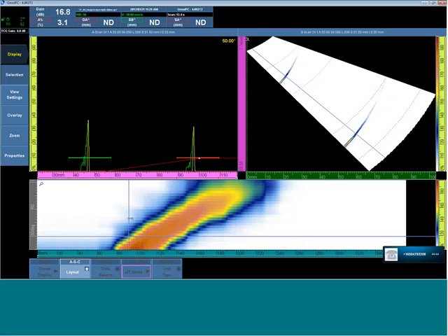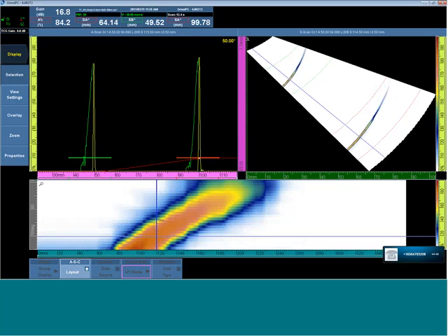So on any A scan, we'll start at 50 degrees. We need to achieve 50 millimeters and 100 millimeters on the block. That's only possible if a wedge delay and velocity are accurately entered into the software, either through the wizard or through the process of the calculator initially in the group setup wizards.